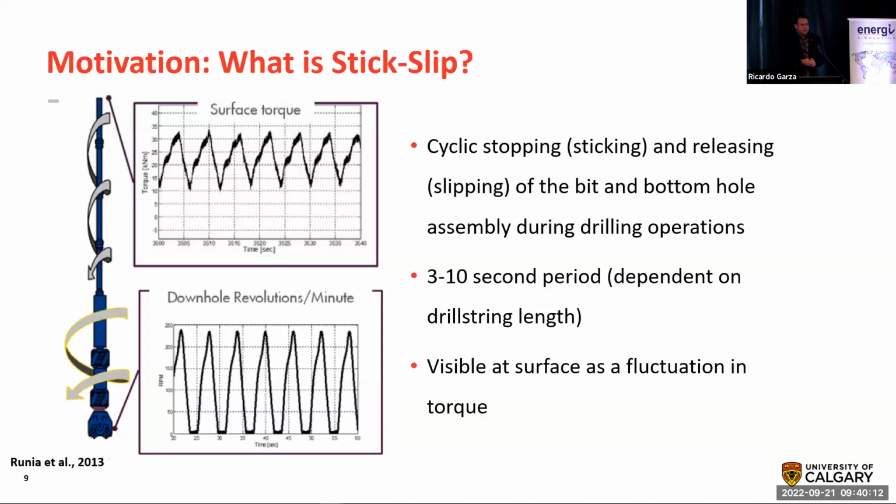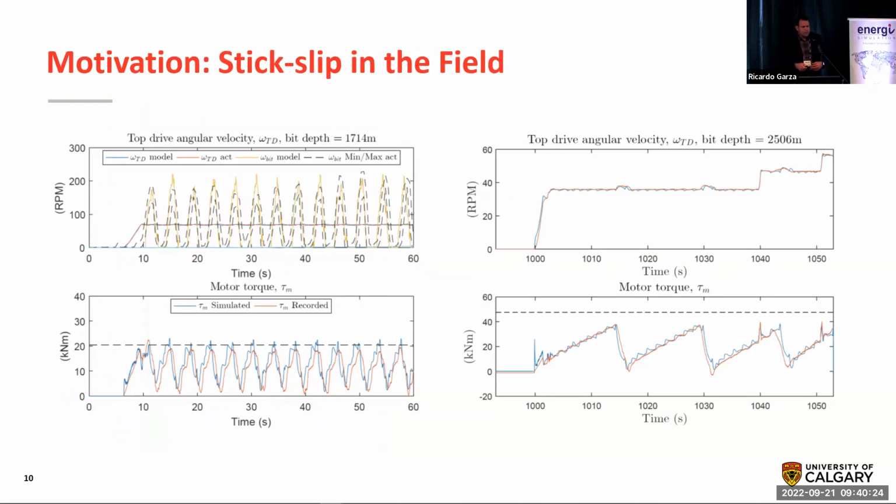In the simplest fashion, you just have a mass on a spring, and you have a damper, and that's your numerical model. If you have a more complex wellbore, though, that model doesn't really work. So here are two examples of field data with stick slip. The example on the left is a more symmetric, typical type of stick slip, where you start rotating at the surface. Surface RPM is around, say, 80, 90 in this case. It's that little narrow red line.